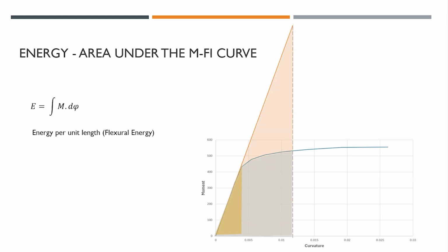The area under the moment curvature curve is the energy per unit length, the flexural energy, because that's the strain. This is related to flexure. So we have flexural energy, and then the same thing. It's the portion under the curve that we can determine, and that is the elastic if it goes straight, and that is the ductility. So energy reduces. Because energy reduces, that means the failure will not be sudden, and the release of energy will be less. It will be less catastrophic.